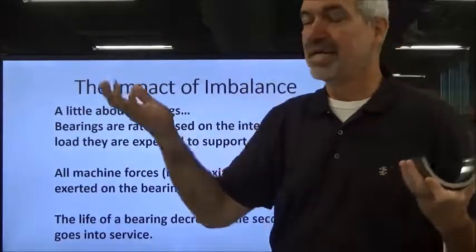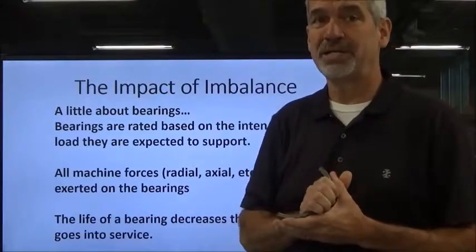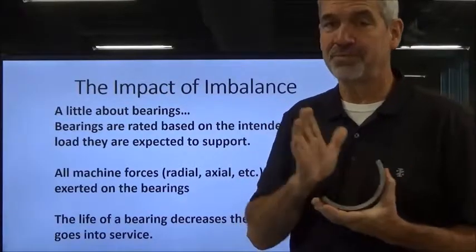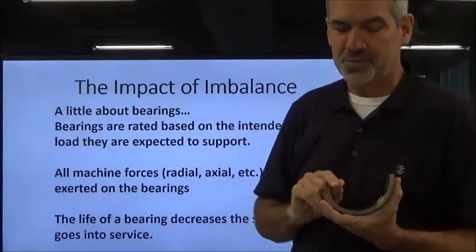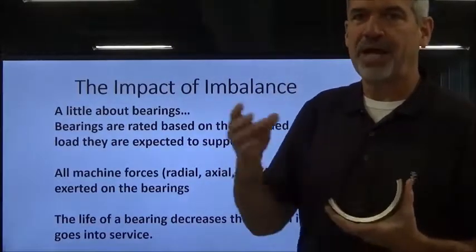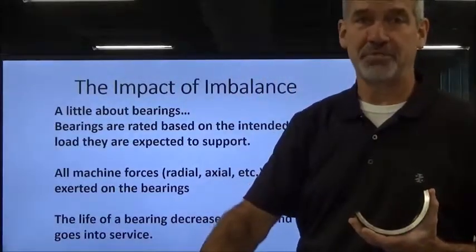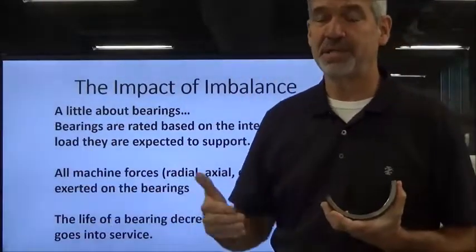I even checked some of the other blowers, and they were running right. So I went back, and bottom line is I had to get those mechanics up there and have them change that bearing on Monday morning. They were ready to string me up, and rightfully so. But here's what saved me. So we got it changed, put the new bearing on. We fired it up immediately. Vibration levels way down like they should be, like I was expecting to see them that Monday morning.